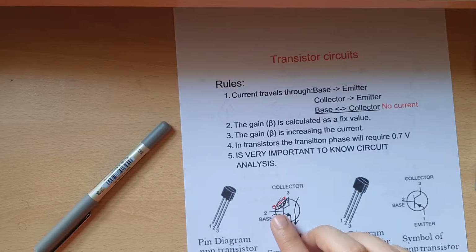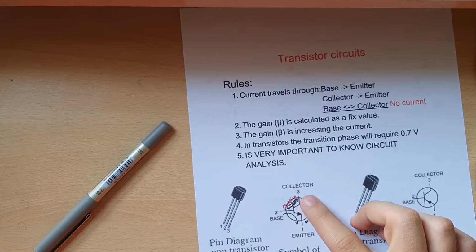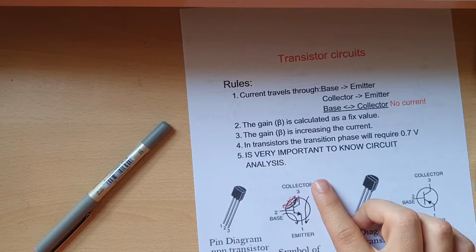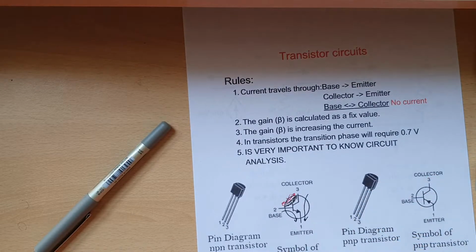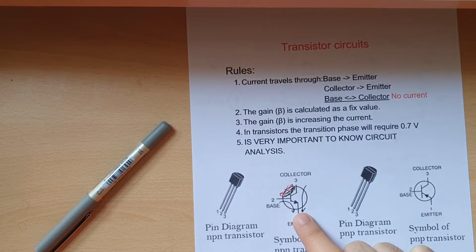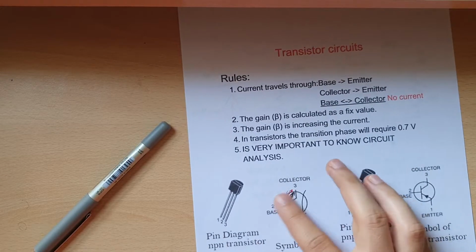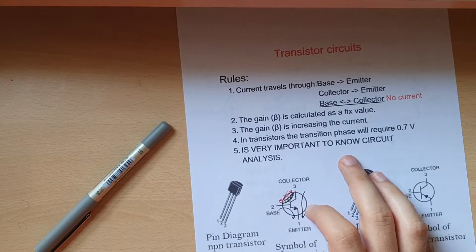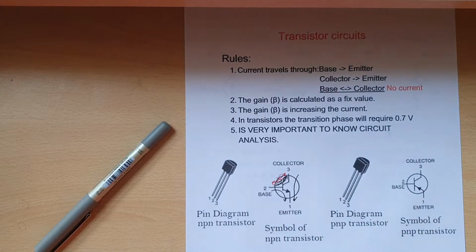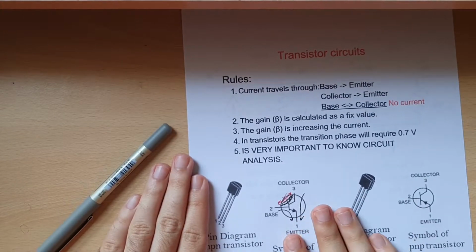And here's where the transistor comes in helping, because you have the small current from the logic gate, but then the transistor will make it into a big current by collecting from its own source, which can be like any voltage, it can be even 9 or 10 or 20 volts if you want, and that amplified current will just go down from the collector to the emitter. And again, transistors are very useful and really easy to play around with and to amplify the current once you learn them. The problem is that I didn't really learn them perfectly and you'll see in a second why. But anyway, when it comes to one transistor, I think it's pretty simple.